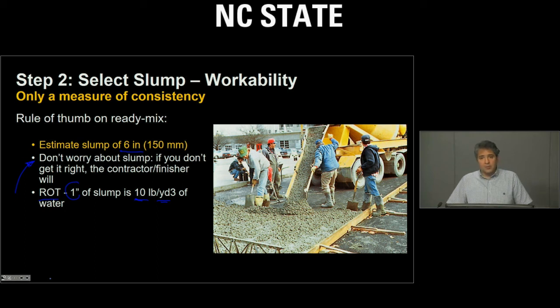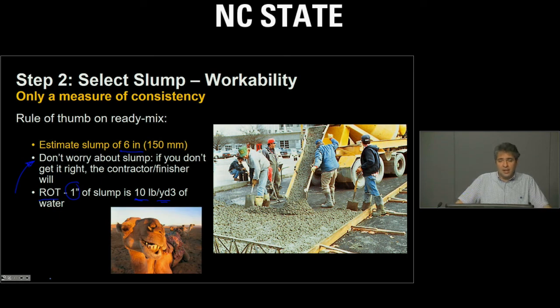And what you will realize if you spend a little bit of time in industry is that concrete trucks are like camels, and they hide water in funny places. And if the concrete mixture is too stiff, they will use that water. You do not want that to happen.